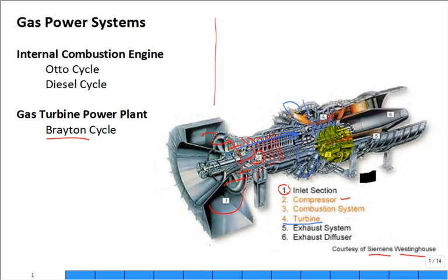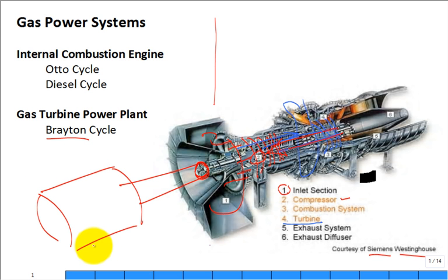You're going to pass it through there, and it'll then generate mechanical power in a shaft, and that shaft is connected back to the compressor. So that's how the compressor runs. It's on a shaft. And if there's excess power, well, then you come out to this flanged interface right here, which you would then hook up to something. Here, if you're making electricity, you hook it up to an electric generator.